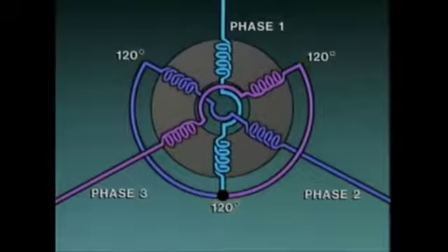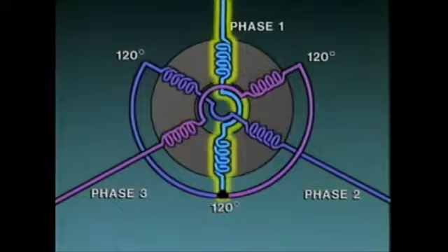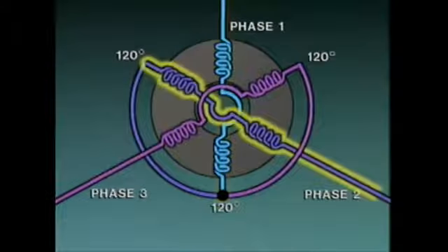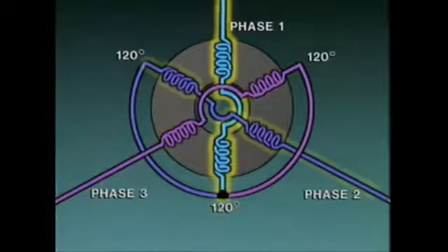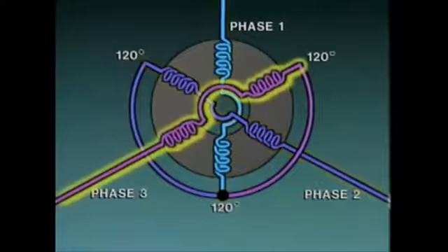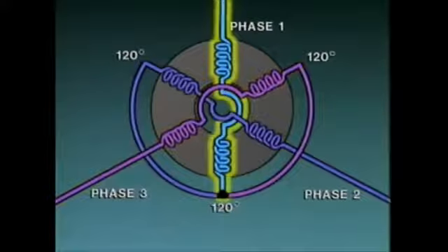As alternating current flows through each coil pair, magnetic fields are created just like they were for the simple AC motor we looked at earlier. However, since there are 3 coil pairs, the stator always has 3 north poles and 3 south poles. As current flow through each coil pair increases, decreases, and changes direction, each magnetic field increases, decreases, and changes polarity. Because the coil pairs are 120 degrees apart from each other, the net effect through the complete three-phase cycle is that the overall magnetic field between the stator coils rotates.